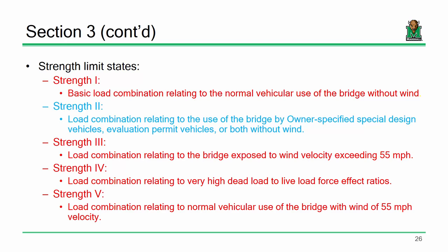Now, the other three combos are related to either construction or wind, okay? I might show you a video next time of what can happen during construction when you've got heavy winds and you don't brace effectively. But Strength 3 is saying, okay, we've got normal use of the bridge, but it's being exposed to large winds. Now, that can be a big consideration. Usually in its finished state, we like to assume that all that wind gets transferred into the deck, into that diaphragm action in the deck, and that deck is so stiff, nothing's going to happen.